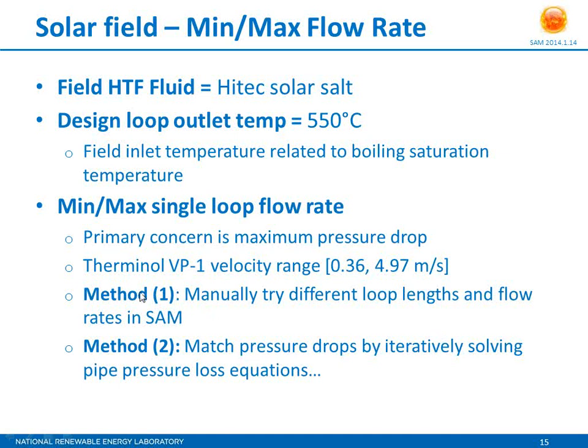But as an engineer, I kind of like to come in and say, well, can we actually predict or understand what the methods are or what the actual equations are that might drive this? So the second method is let's match the pressure drop by iteratively solving the pipe pressure loss equations that some of us might remember from our fluid mechanics or heat transfer days. So this is actually what we're going to do.